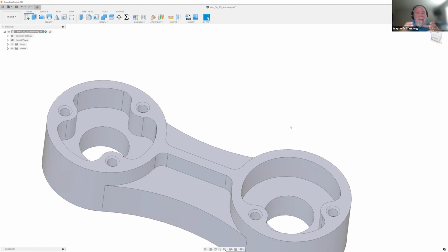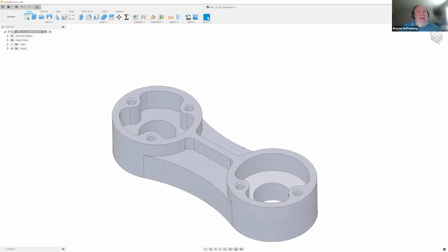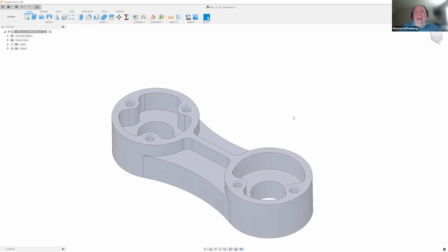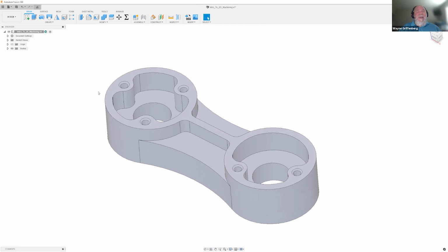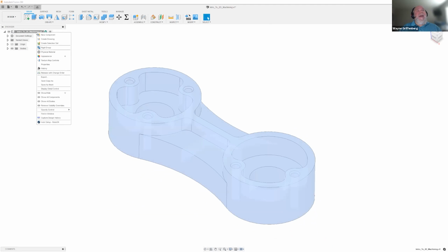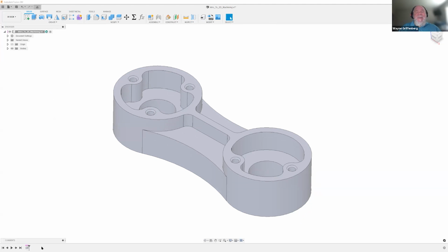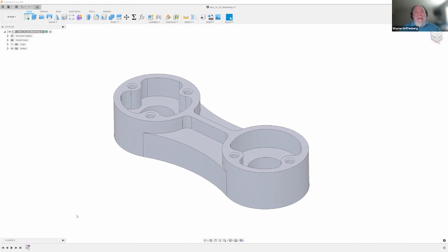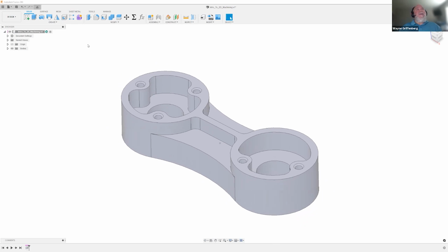Again, if you want to make some soft jaws and then have it removed, do a Boolean remove, as we call it, combine, you could do that really easily and make those jaws match exactly what you have going on in the model. So I'm going to come back. We're going to spend a little bit more time making some changes in here, but I want to show you that CAM workflow, or the integration between CAD and CAM. I'm going to start to select and create or capture design history. This is a good, important part if you want to be able to capture those changes going forward. So if I capture design history, now I go to change it, I can always see a timeline in the corner here.